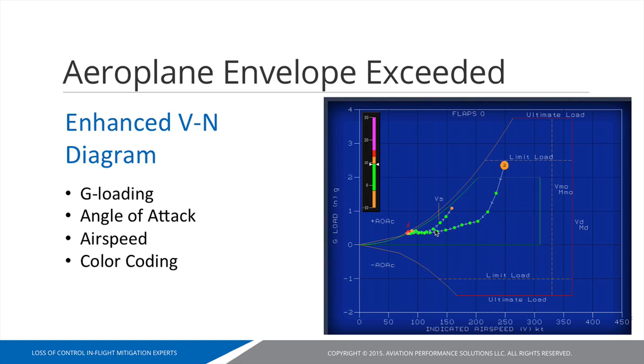These dots are presented based on what is going on in the entire scenario, not just based on this one diagram. When the green dot is being plotted, it means that no other violations of flight envelope, G, or other factors that are being recorded, such as rudder pressure and other things, are being exceeded. So technically speaking, the green dots would represent how the airplane is being flown in a valid, safe area of the envelope.